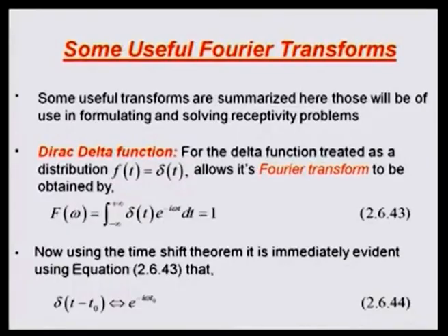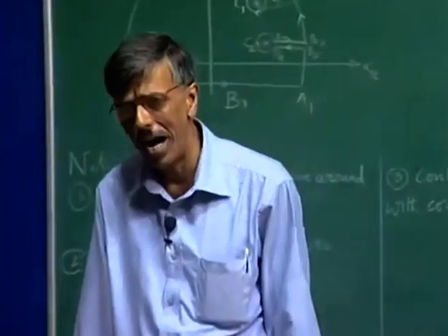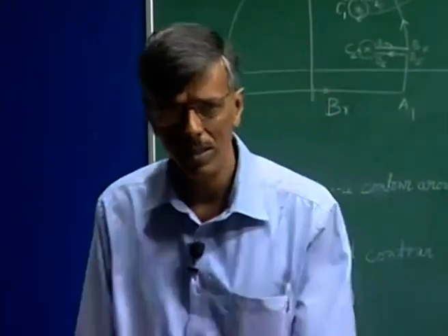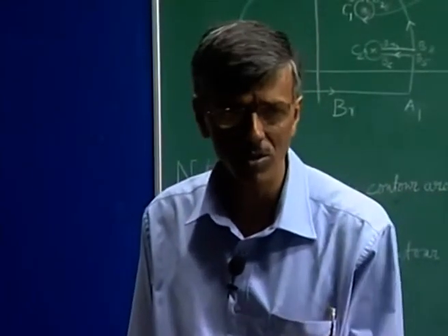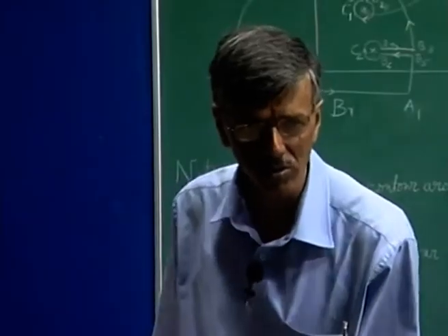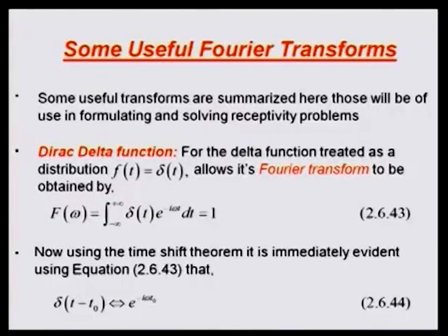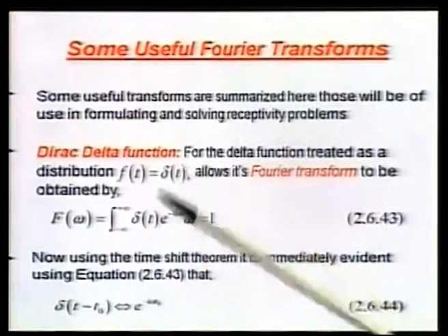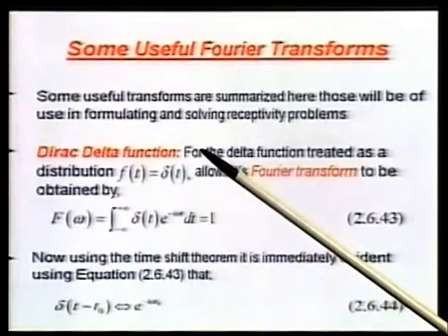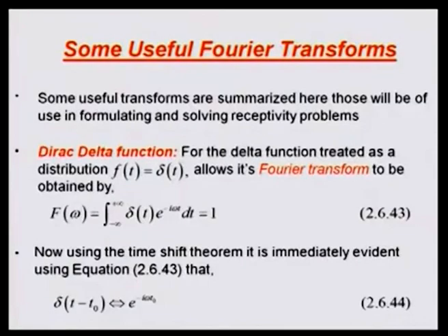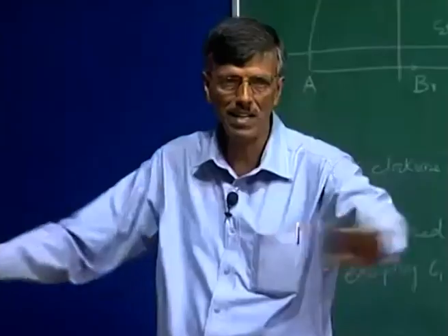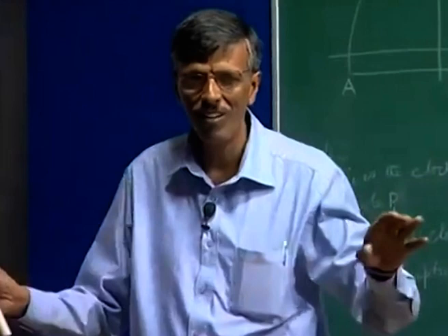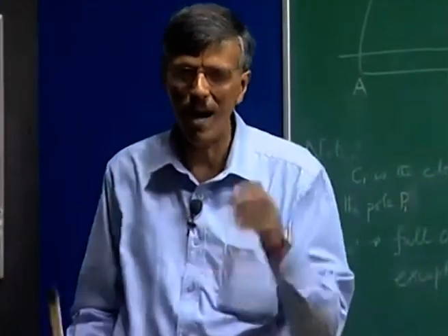Okay. This is what we have talked about in the past when discussing frequency response versus impulse response. As you can see, if I create a delta function in the physical plane, so I am just giving an excitation at t equal to 0, that fills up my frequency plane completely, and they are all weighted equally, there is no bias.